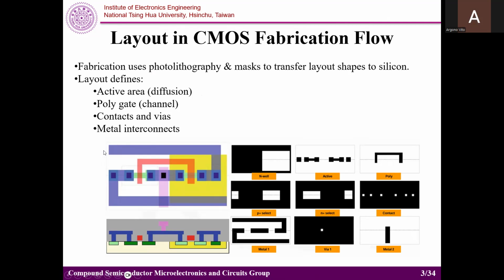So imagine this is a silicon wafer, and you need to define this area on top of it. This is the nwell mask, the active is the blue one, and the poly is the red one. This is the top view, and this is a cross section.